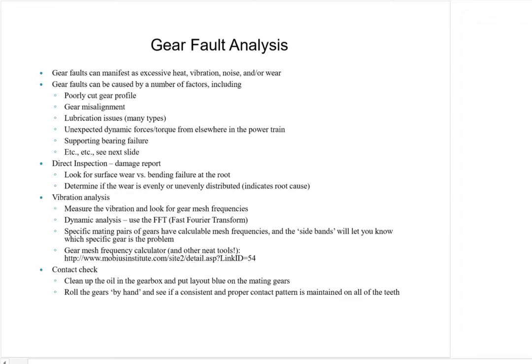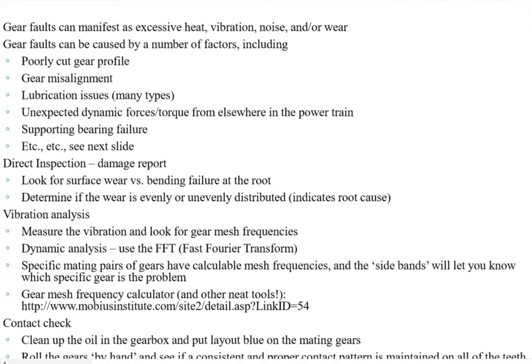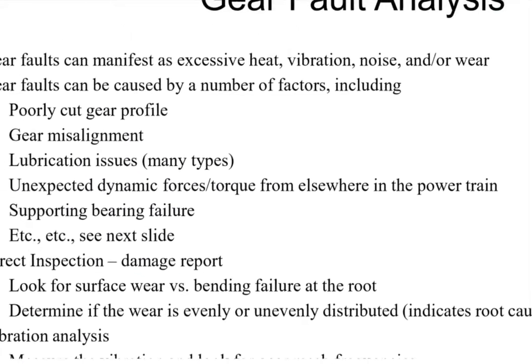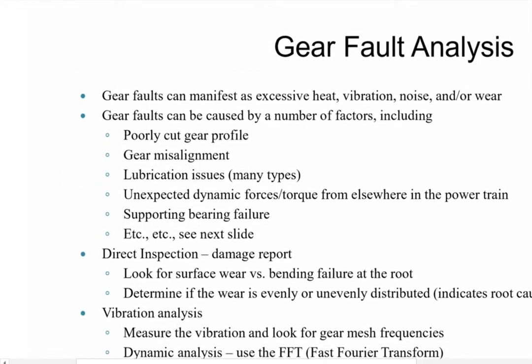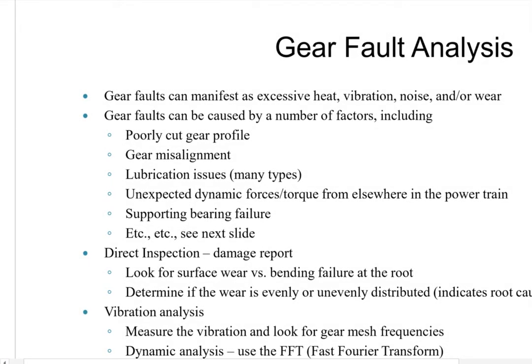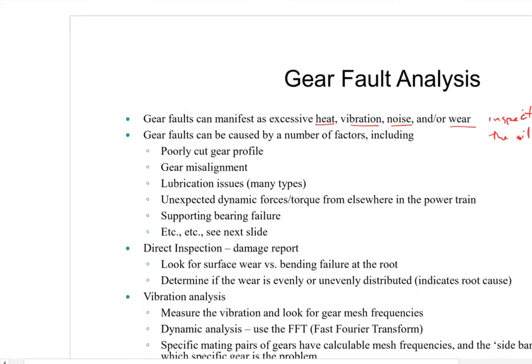Some more practical information, gear fault analysis. This is also not in the book. When gears fail, sorry for the small print, we can zoom in on this a little bit. You're generally going to have heat, vibration, noise, and if you can see it, wear. You might get chips in the oil. Inspect your oil. Always inspect the oil.